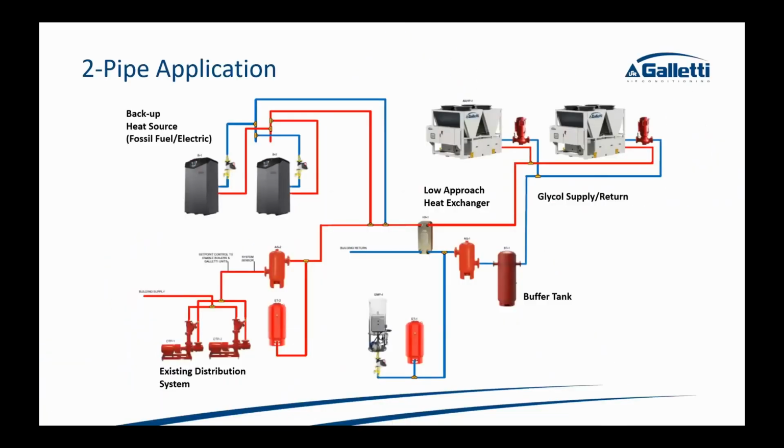So, enough with the product specifics. Here, this just shows that hybrid approach. Once again, this is showing a two-pipe system, connected to our heating circuit with the backup boilers. We have our heat exchanger getting cold water from a return line, preheating it, or possibly even just satisfying the load up to a given temperature. If we do need additional capacity, then we would just stage on the remaining unit. That can be done by set points in the heat pump chillers, or it could be third-party control, or you could have it as simple as just programmed onto a boiler of when to kick on or kick off in terms of outdoor air temperature.